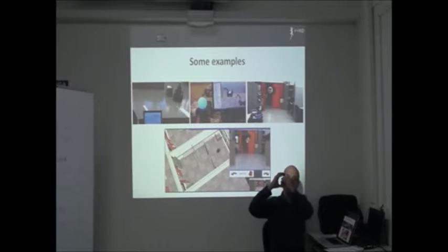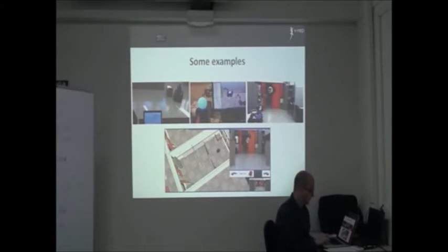You say, okay, the position in space of my PlayStation Move remote is mapped to the position in space of the end effector. So I can drag the end position wherever I want, and you will have to compute the inverse kinematics of the manipulator. But this is handled by VREP, as we can see.